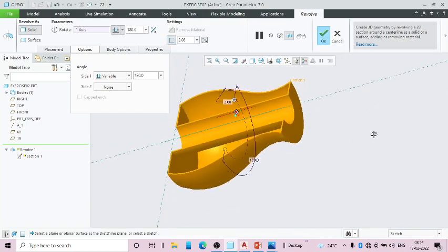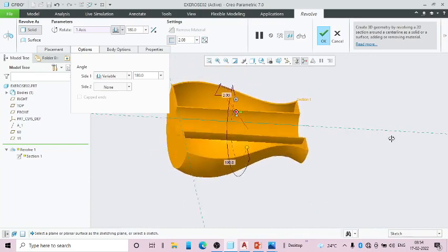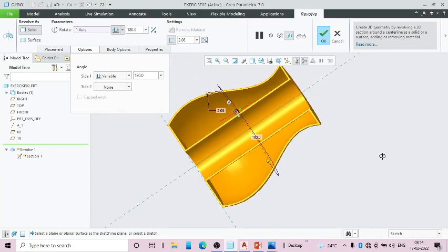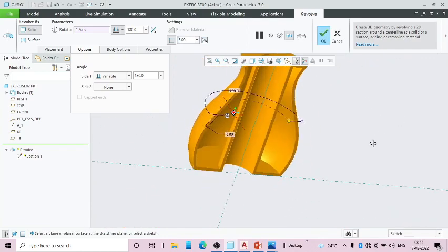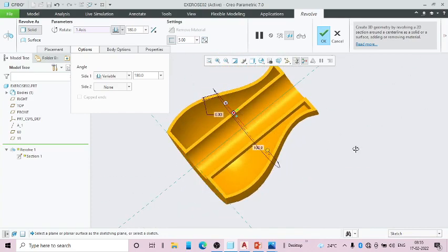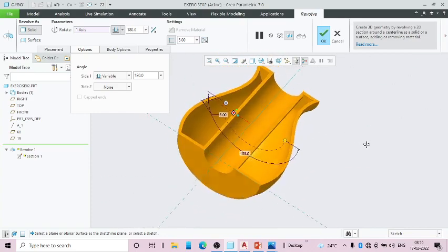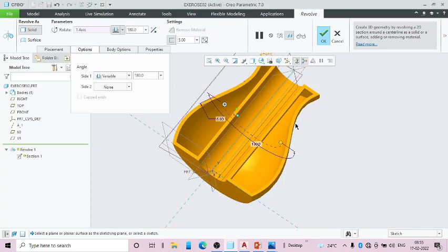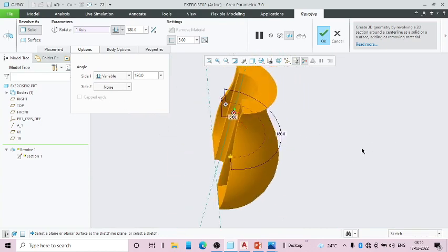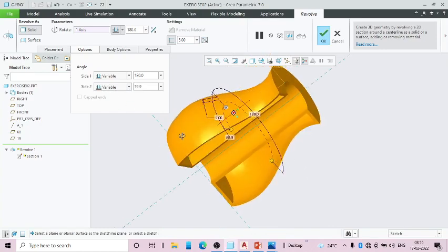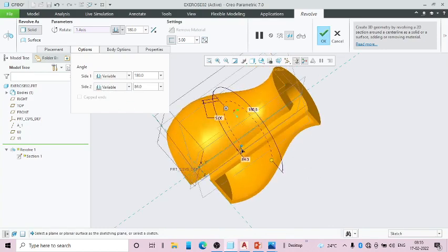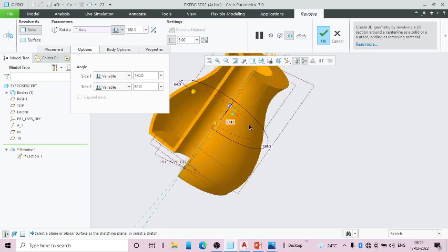So you can see here, so beautiful option here. I can add some thickness, 5 mm, so that it is very much clear. So to make objects which have thickness features, you can easily add this. Now let us say variable, you want to add some more inside, it's possible. So that's all about Revolve.